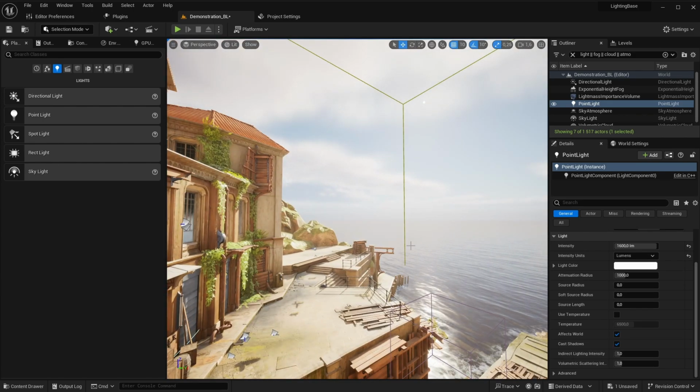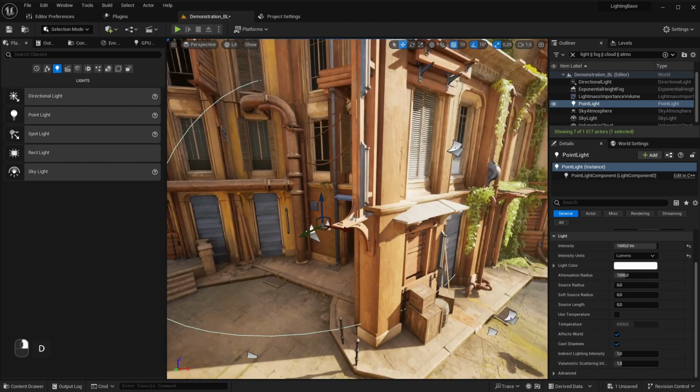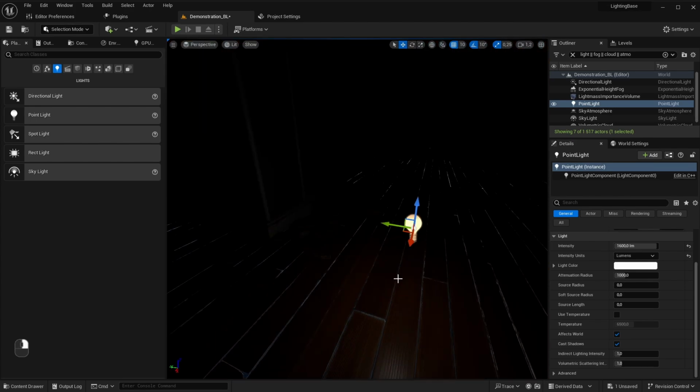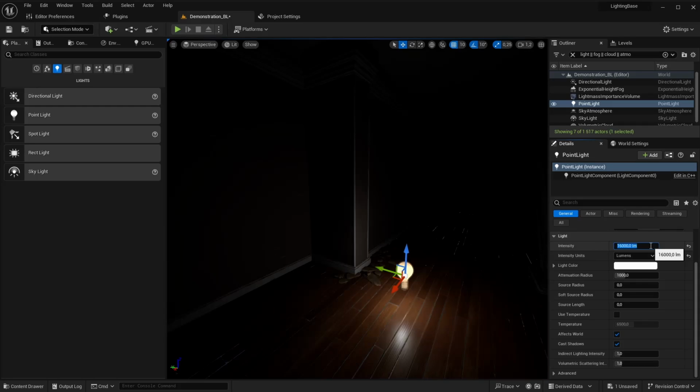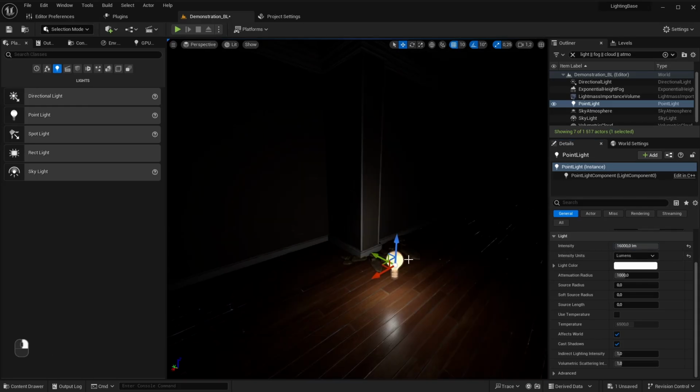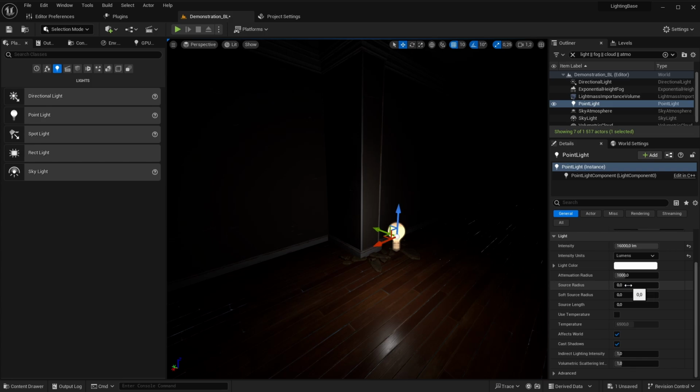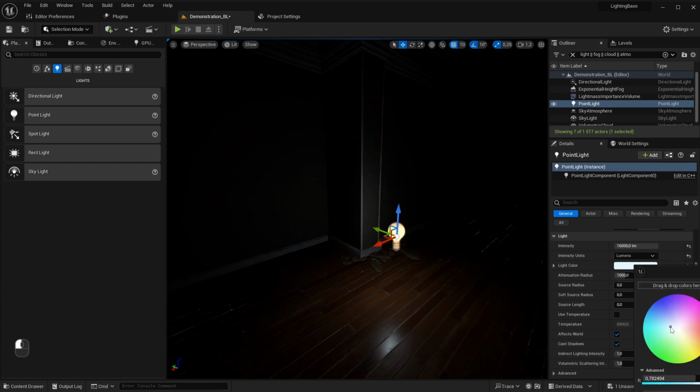And if you want to use physicalized units, you can see actually the range of energy of the lights and the difference between them. So in this case, I'll actually make the light source more powerful. So let's say 16,000 lumens instead. Let me also change its color directly by using the light color option. So if you want to use some specific colors for the lights, for example, if I want to make it green, I can use this here.